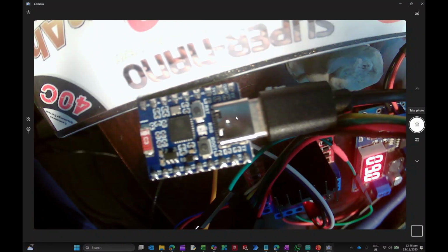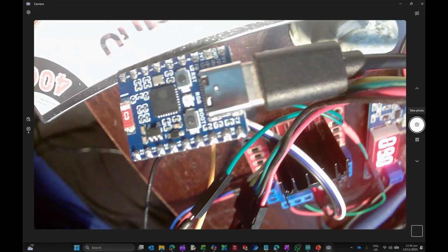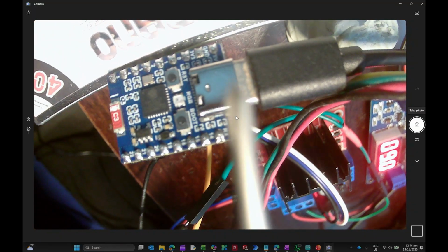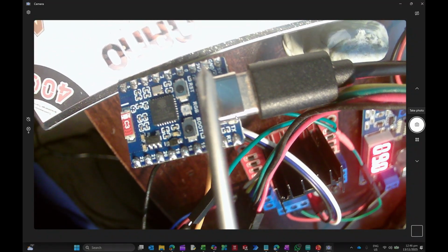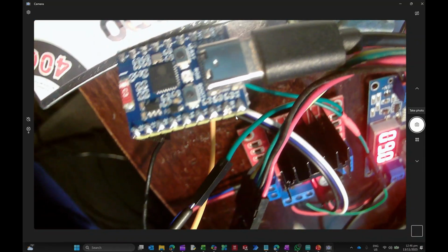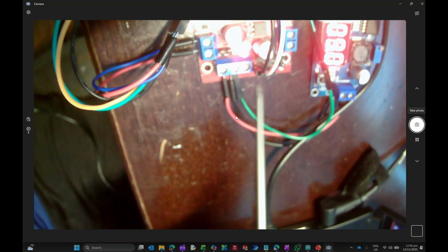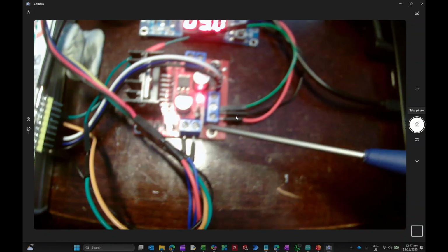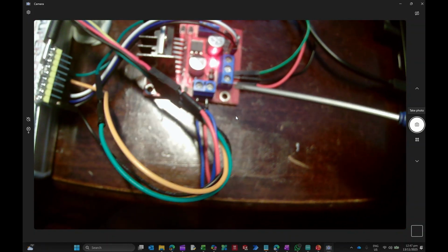It's a bit poor, kindly bear with me here. Right, so as you can see, there is the ground pin right there, the second pin towards the left, right? So that's the ground pin, and that ground pin gets connected here to the motor driver common ground, okay? So then the output, I'm basically using, this is a bit disorienting, apologize, but then the output